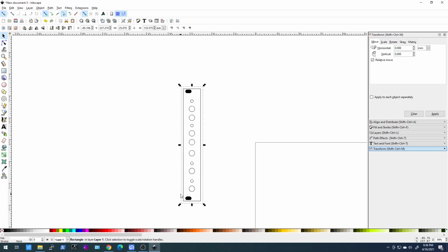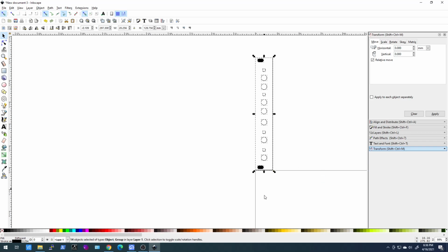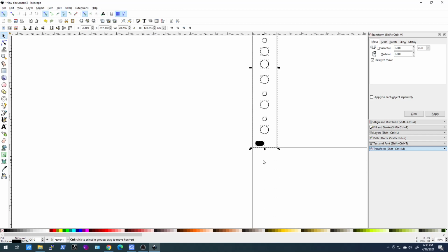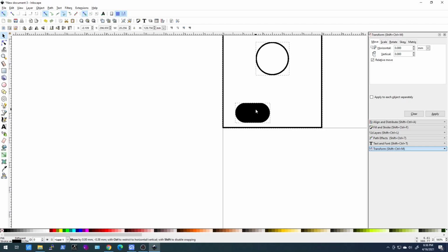So go ahead and highlight that and delete it. We don't really need that. I'm not sure what it is, but it comes from EasyEDA when you export the SVG. Now, normally when I work in Inkscape, I like to get rid of the page border, but it's useful in this case. So what we want to do is place our panel right on the corner there. You can kind of split the line there.